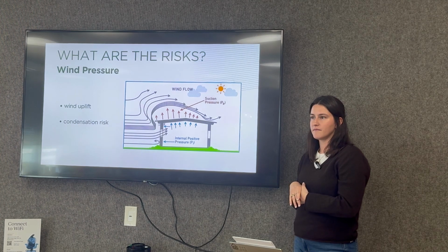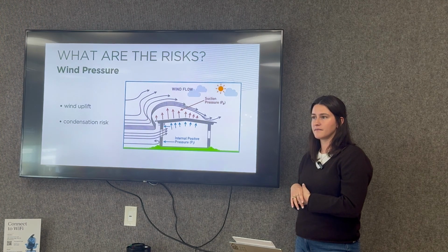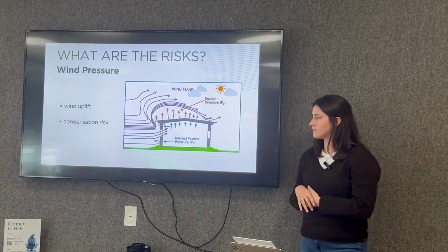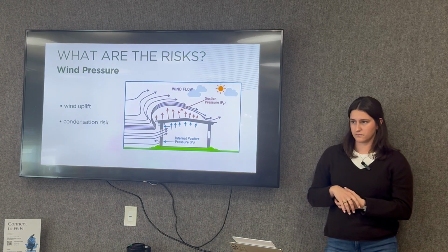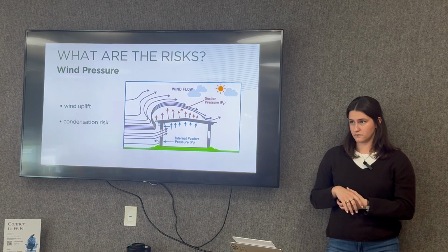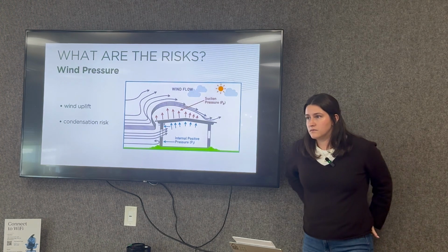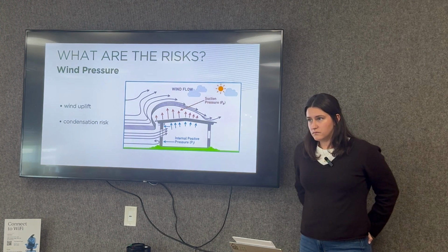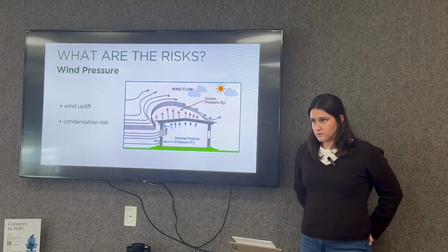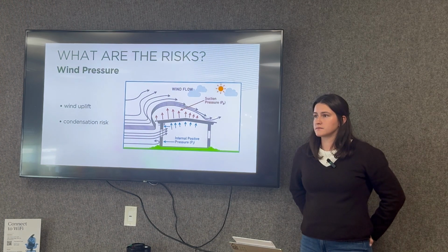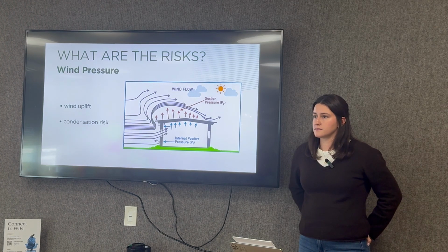So John, to your point with interior pressurization as it relates to wind uplift, I see that the interior positive pressure coefficient is one of the considerations as you follow through all of those steps in ASCE 7. Right now, it does not take into account any kind of pressure equalization from the interior. I think as it becomes more common, maybe in future code cycles, it may be added, since ASCE 7-22 doesn't have that provision. We still use ASCE 7-16 in Europe. Who knows, maybe 2, 3 code cycles down the line, if it becomes common enough, then maybe something.